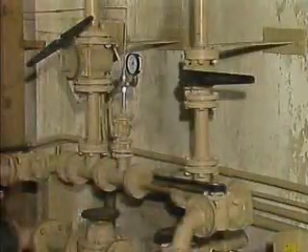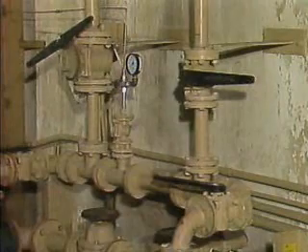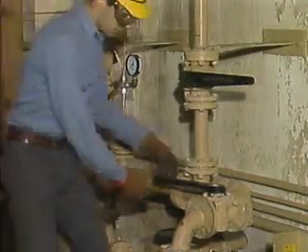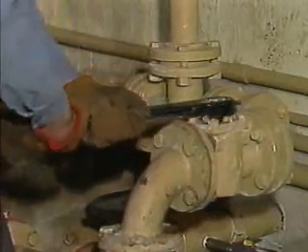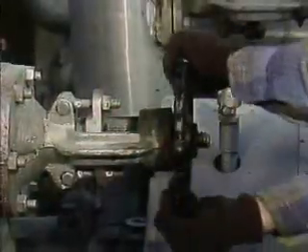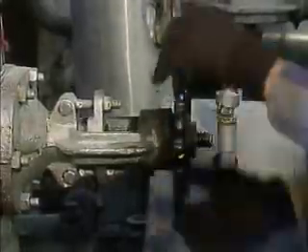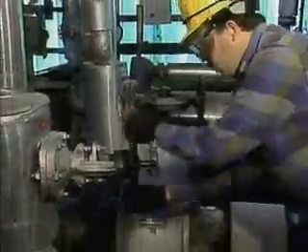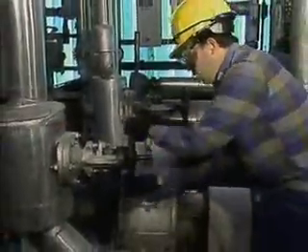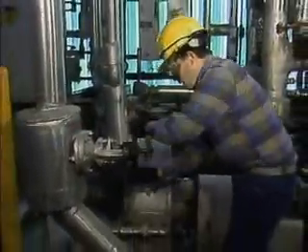If a valve is opened with a single operating lever, such as the handle on a plug valve, simply move the handle in the open or the closed position to operate the valve. If a valve has a hand wheel, use both hands, placing one on each side of the hand wheel, to open or close the valve. This enables you to apply force evenly to the valve. If force is applied unevenly, the valve stem can be twisted, bent, or broken.